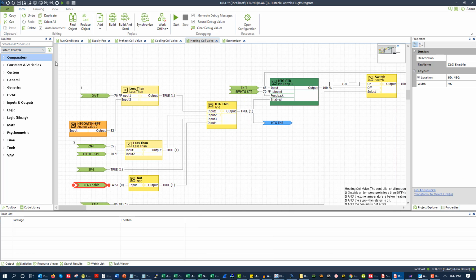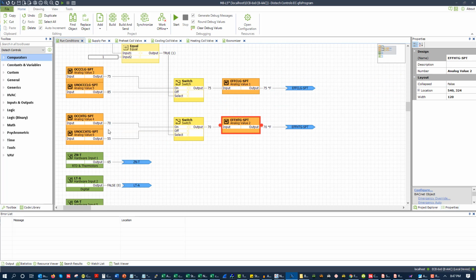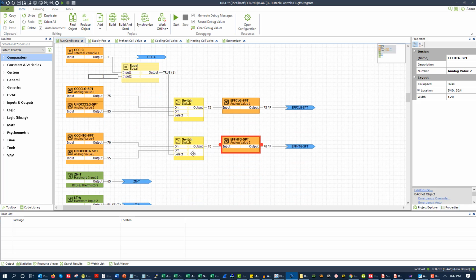And what I'll do is I'll write my programs as I work through the sequence. So what would happen in my programming process, and we'll explore this more later this week, is to add physical points and physical inputs and outputs first, then add our set points, and then add our Boolean logic, which is true-false logic, and then go and add our analog logic. Now, it doesn't always work that way in life and in programming. Sometimes you iterate through those steps multiple times. Sometimes the steps are a little fragmented. But if you have that general process, you'll tend to turn out some pretty good code.